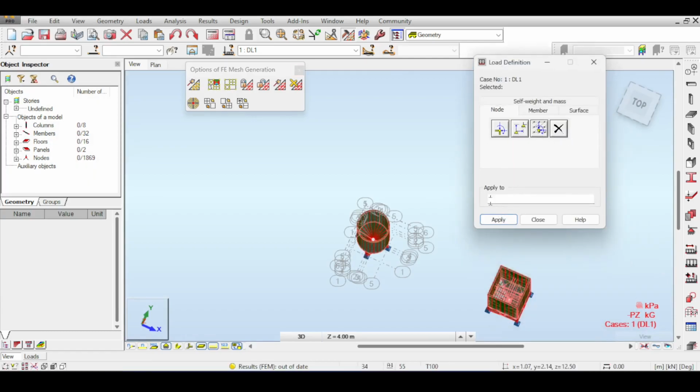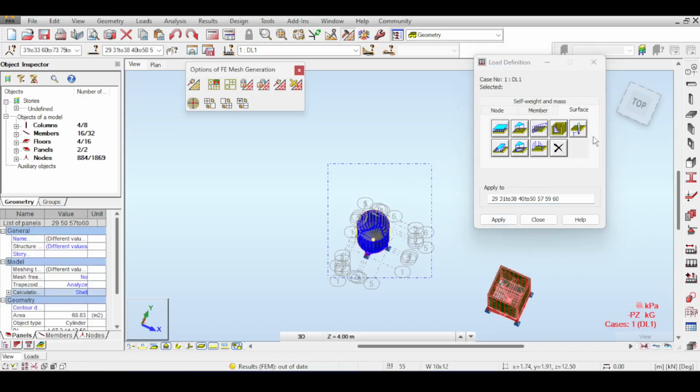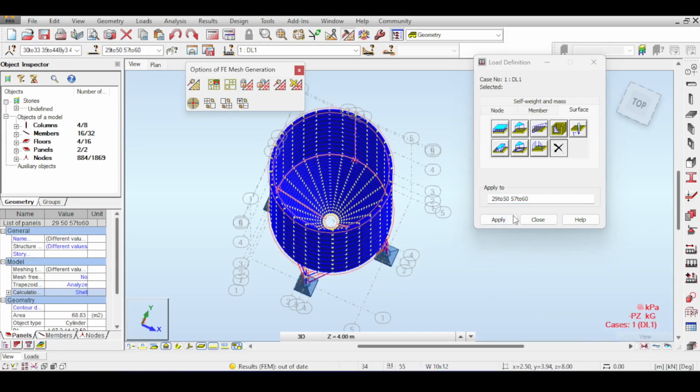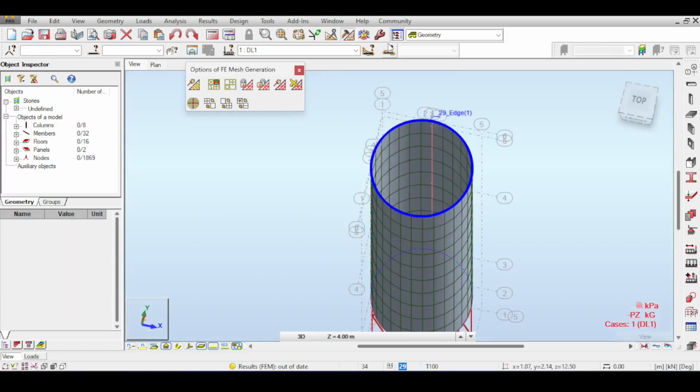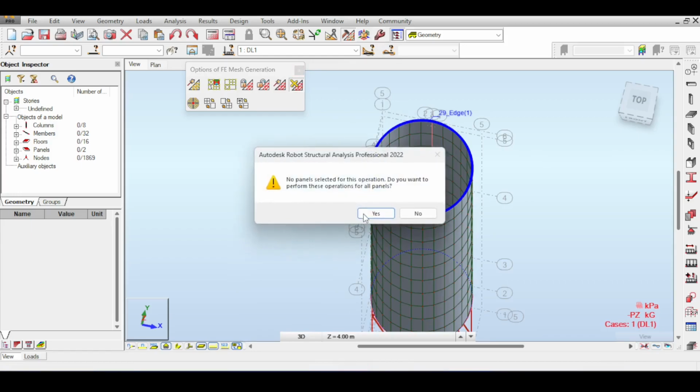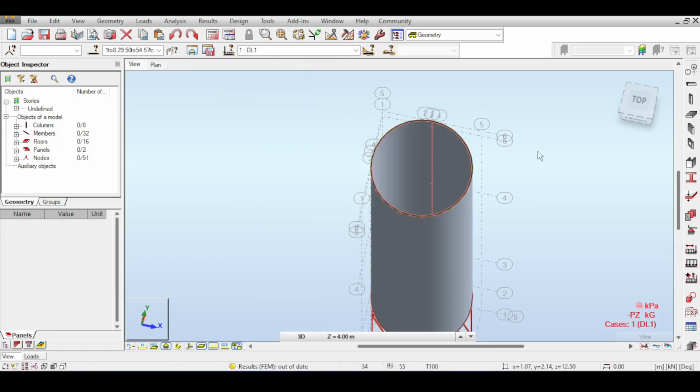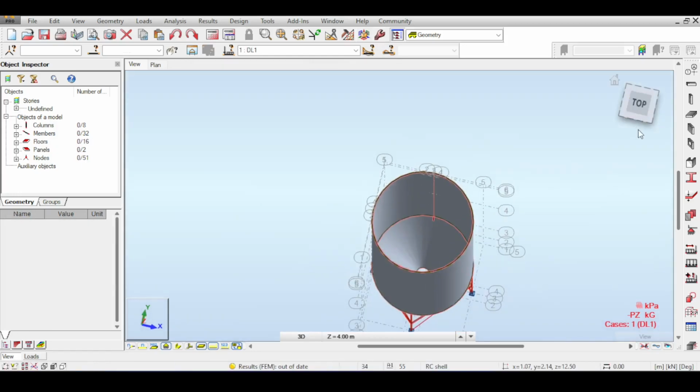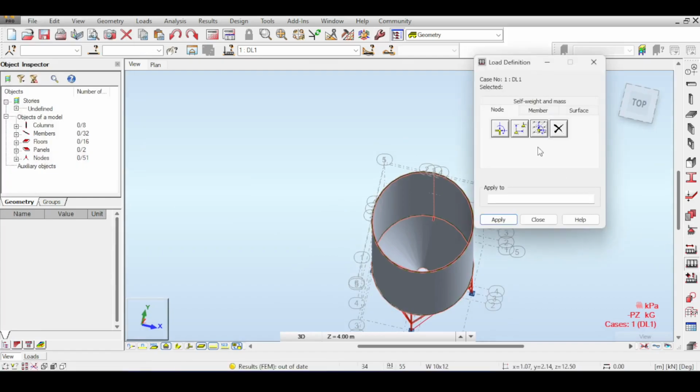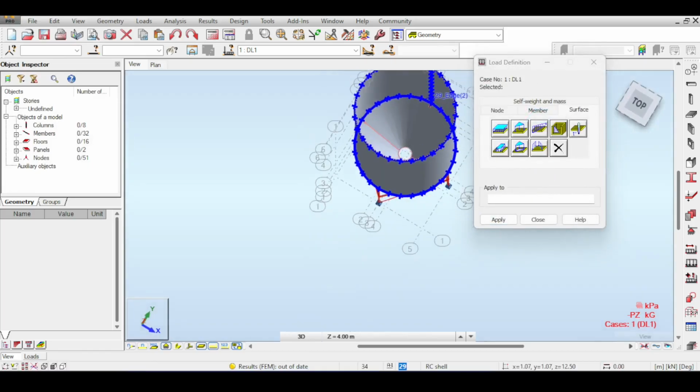First of all, let me make sure that I don't have any surface loads on this thing. So I select that, click X, click apply, just to make sure that no loads are applied now, except the own weight. Going on with this, of course, I don't need a mesh now because the mesh should not exist when you are modeling. If you go here now and, for example, select a load and select a surface load and try, contour is out of the question because you don't have points to grab in those contours. So it's not really a good idea, to be honest.